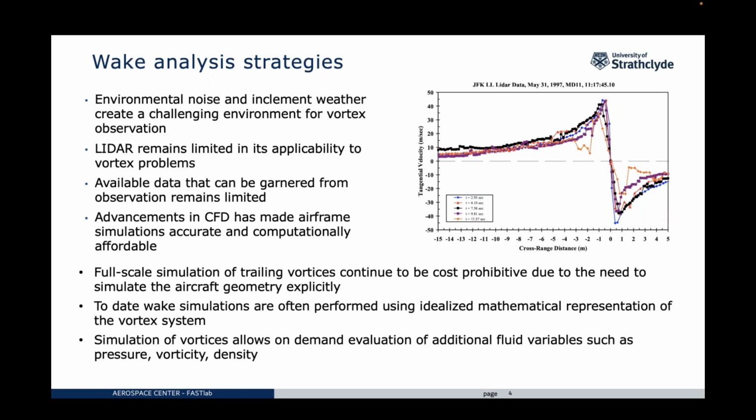If we want to simulate wake vortexes, well, there's a couple of ways we can do that. We can do a full-scale simulation that includes the aircraft geometry, and also a far enough downstream wake region to resolve the flow features of interest, such as the long wave instabilities. But these are incredibly expensive because we have the refined near geometry region, including the boundary layer and the walls. But the wake also has to be sufficiently refined such that we can capture the effects of the wake vortexes with minimal dissipation from the mesh.